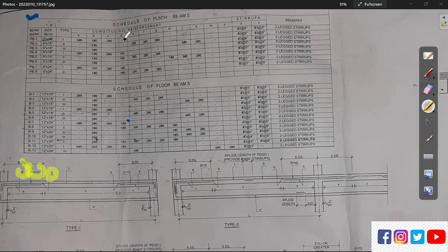So you have to check the extra reinforcement. So B, you can see here, B is 1 number 6 bar, and what is C, like B plus C here, right? So B plus C is 2 number 6. So one is an extra bar, you can see here. So this B plus C, B is 1 number extra bar and C is 2.